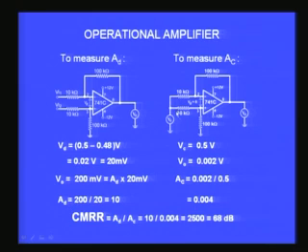In the second case, I have connected the two input terminals and applied a constant 0.5 volts. Now, what is the output voltage? I measured 0.002 volts or close to that. So, what is the gain? Output voltage divided by input voltage, 0.002 divided by 0.5, which is 0.004. The gain is 0.004. Therefore, I have now got AD, which is 10, and AC, which is 0.004. That means it is a very small value. The common mode gain is a small value. It is not an amplifier at all, it is actually an attenuator. It has reduced the output voltage.